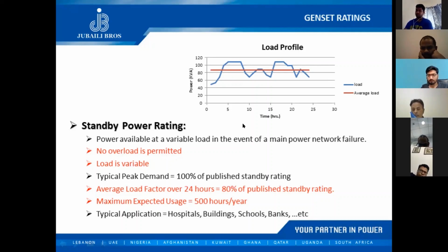If you look here at the graph, at hour 5, I reached 110 kVAs. I'm using it at 110 for more than 1 hour, reaching around hour 8. So there's 3 hours of usage at 110 kVAs. That's 100% of my standby rating. There's no overload. This is fine, given that my average is not exceeding 88.